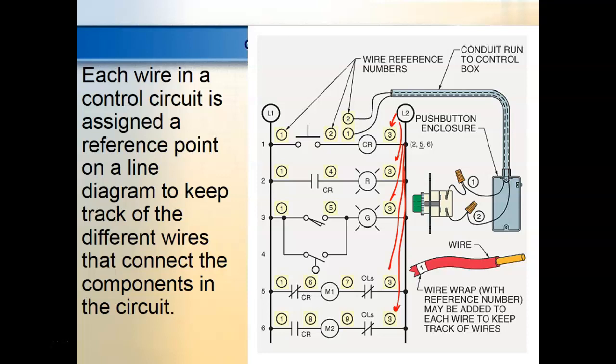In fact, that might be my problem: I measure voltage at my transformer, but I've got a broken wire down here somewhere, right? You understand? Well, the voltage is good, right? But it's not good where? So you come over here and this wire's broken right there. These guys are not working. You go up there and measure across L1 and L2, and you say, well, L1 and L2 is good, and then you move on. Well, it can't be L1 and L2. They both measure what they're supposed to, but you didn't measure where you should have measured, because these two guys are not working. But I could have measured here or I could measure there, right?